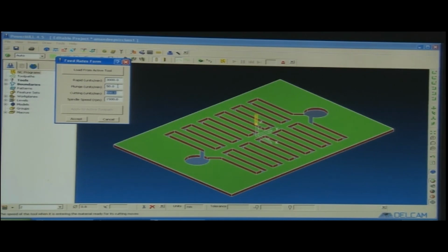When I say final machining, it has to be the feed rate selected for the specific combination of the tool and the workpiece. For instance, we can use the chrome plated tool for mild steel. So, there is a specific combination of tools. Some materials are very hard, like titanium. For titanium we have a specific set of feed rates and plunge rates as well.